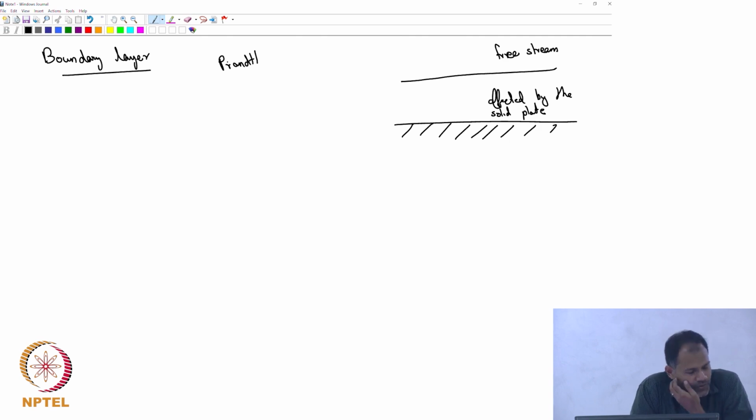So people were initially thinking about it like this. The Reynolds number is defined as the ratio of two forces. What are the two forces? Inertial by viscous forces. And people thought, if we keep increasing the Reynolds number, then inertial forces are going to be much larger than viscous forces. We would think that the effect of viscosity becomes much smaller, we can neglect all the viscous effects, and we can talk only about inertial effects.